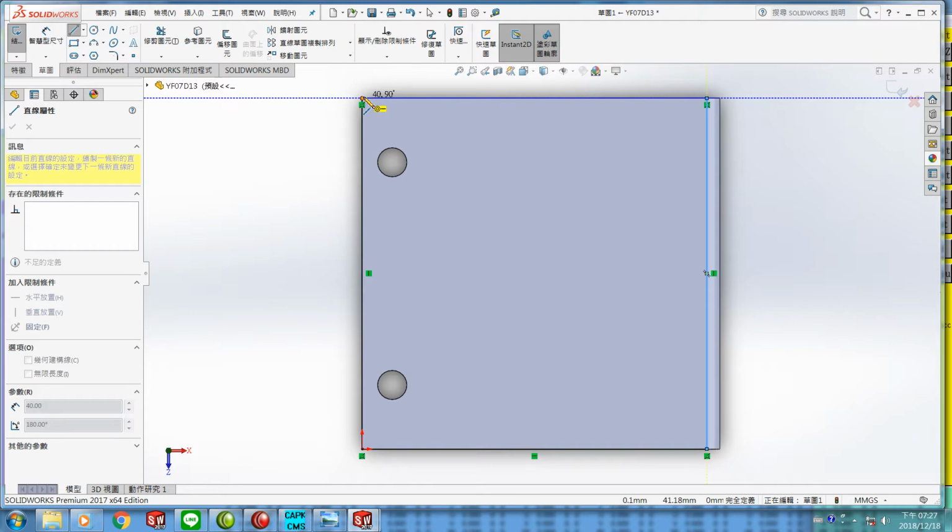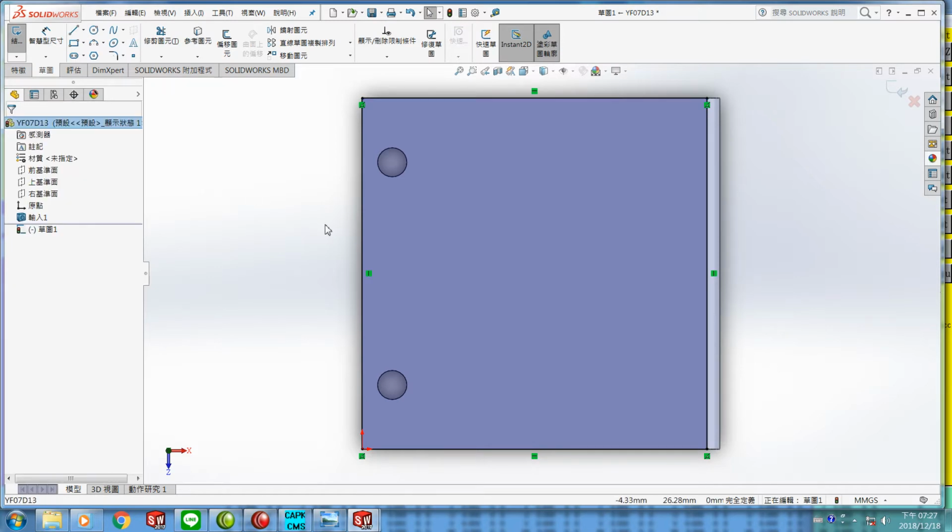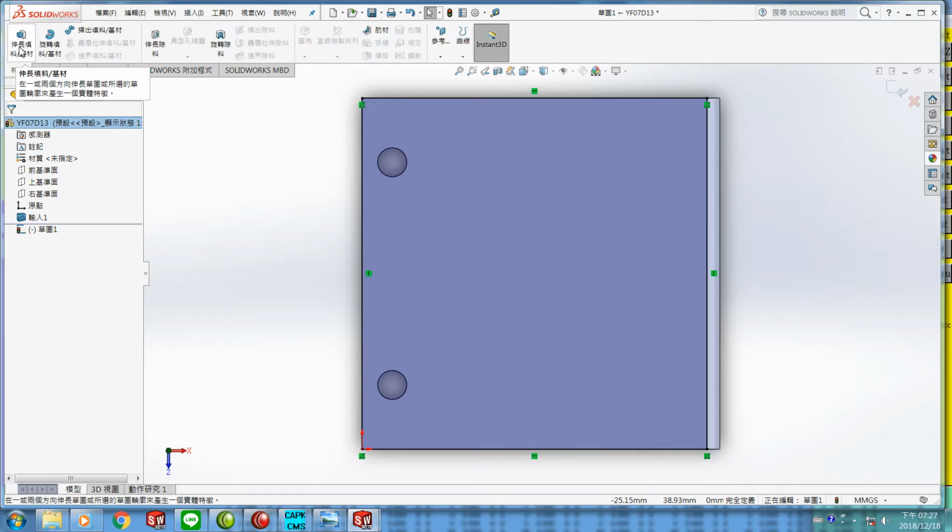the first to create a loop. Okay, press the left button of the mouse. Then you can see the surface change the color to gray. Simply press OK, OK, and then use spatial symbol functions and use extend to fill the holes functions.